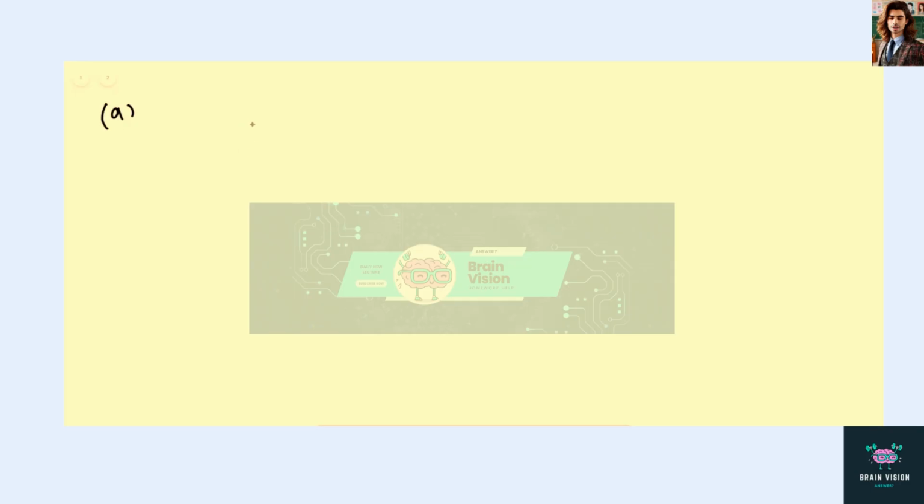So the time constant for the RC circuit is given by equation 26.7. According to that, time constant tau is equal to R times C. Plugging the values of both, we get the time constant to be 132 milliseconds. Take care of the order of the units while doing this calculation.